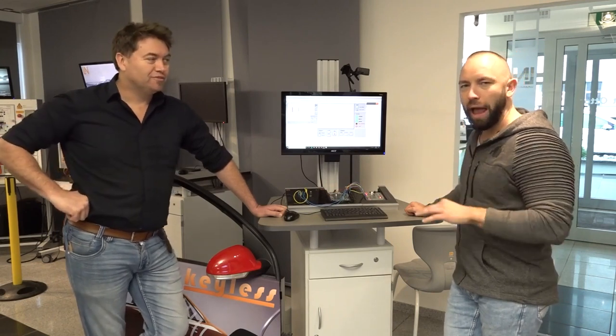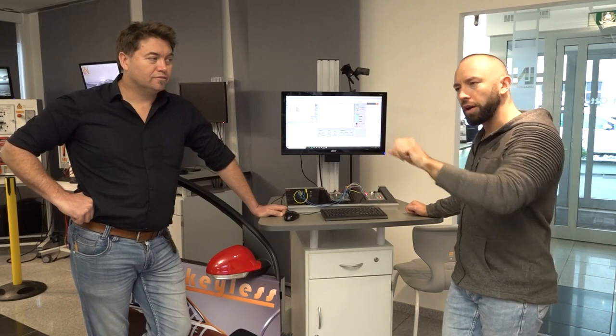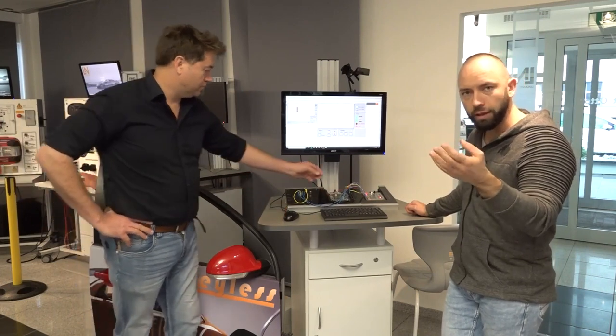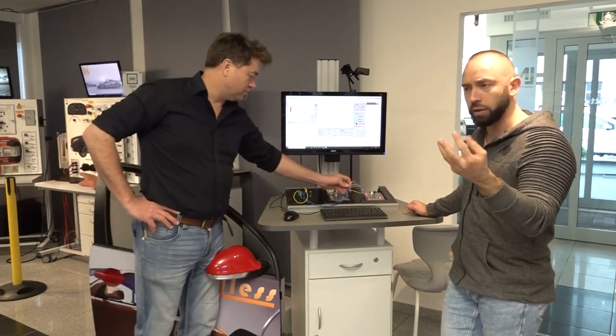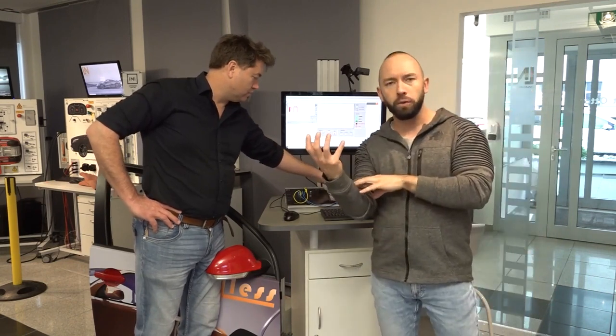And just a small excursus here, side information. This is one reason as well. It may change today as they have different bus systems, but back in the day, LIN bus was always used for adjusting the side mirrors, for example. Why is that so? One reason is the security behind it, because you can easily access the mirror, just remove the glass, and then you basically have access to the cables.